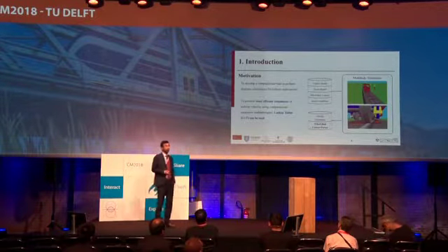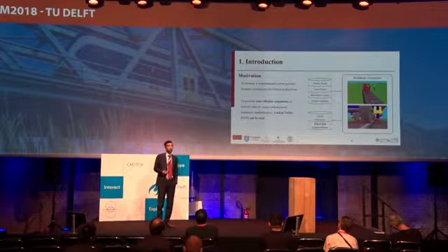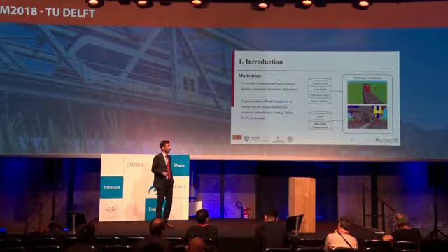And a third alternative is to use a book of tables, which means you invest some initial computation time in computing the relationship between creepages and creep forces for some selected conditions and for some selected shapes of the contact patch. And then during the simulation, you just interpolate this contact table, which can be a good way to obtain good accuracy while having a very small computational effort involved.